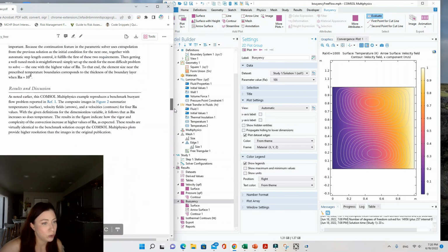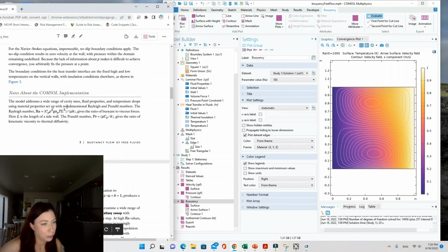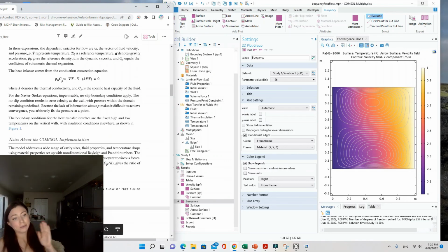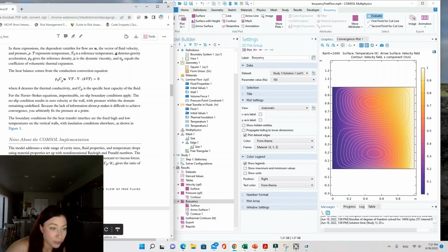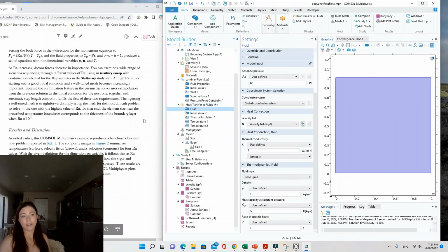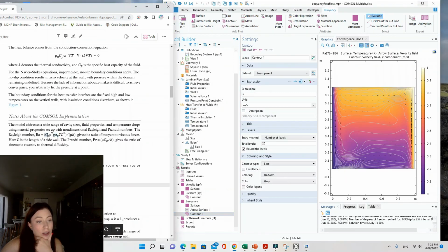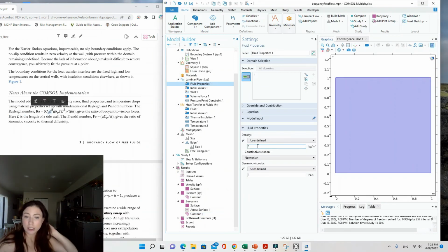Because if we go back to the definition of the Rayleigh number, in the numerator we have Cp, the heat capacity, Cp times density of the fluid squared, times gravity acceleration, times alpha P, times temperature, times the characteristic length cubed, over the kinematic viscosity times K, which is the thermal conductivity. Alpha P equals the coefficient of volumetric thermal expansion, and Cp is going to be a constant, or we're treating it as a constant. For dynamic viscosity and density, we've defined both of those as constant.